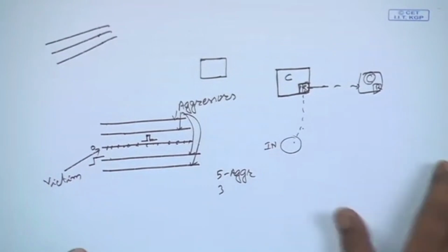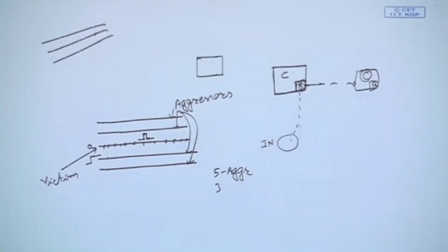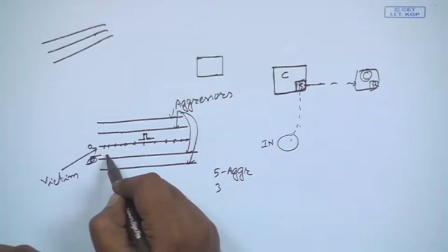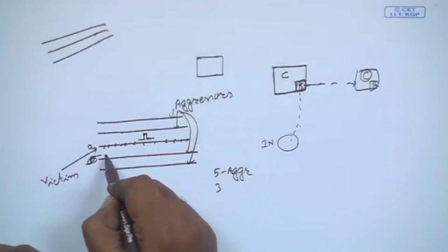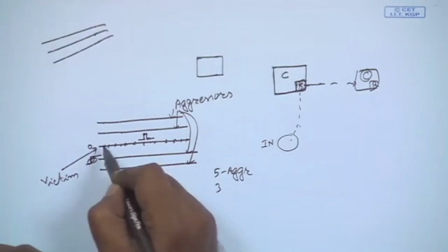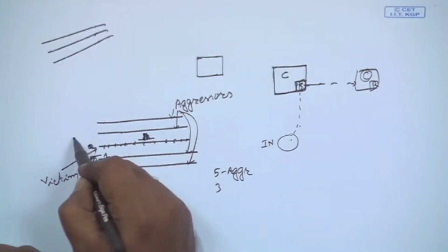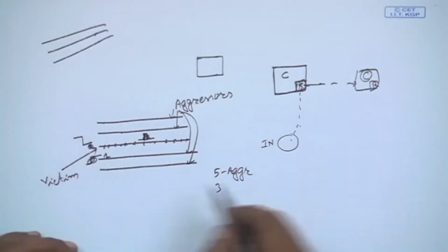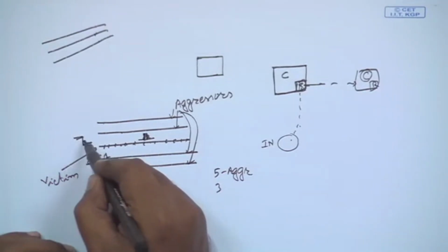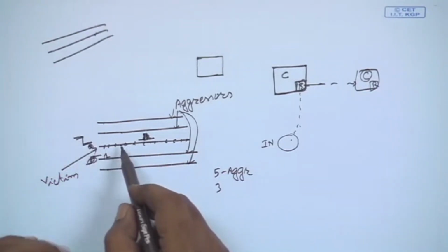This is creating crosstalk, and due to this crosstalk between the lines, the signal levels may be inconsistent at some point. It may introduce some glitch, and also the transition time may change. Say this line is permanently high, and this line tries to make a transition from 1 to 0. This transition will not occur immediately because of the coupling between these two lines.